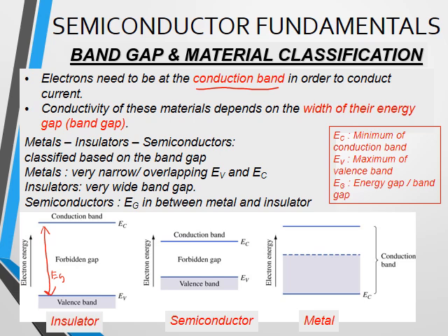Comparing insulator to the semiconductor, the energy gap of the semiconductor is smaller. This means the energy needed for the electrons in a semiconductor to move from valence band to the conduction band is less than that of an insulator. This narrower gap allows external supply of energy to provide the electrons enough energy to jump to the conduction band. Thus, under some condition, such as with an applied bias or voltage, the semiconductor can conduct current.